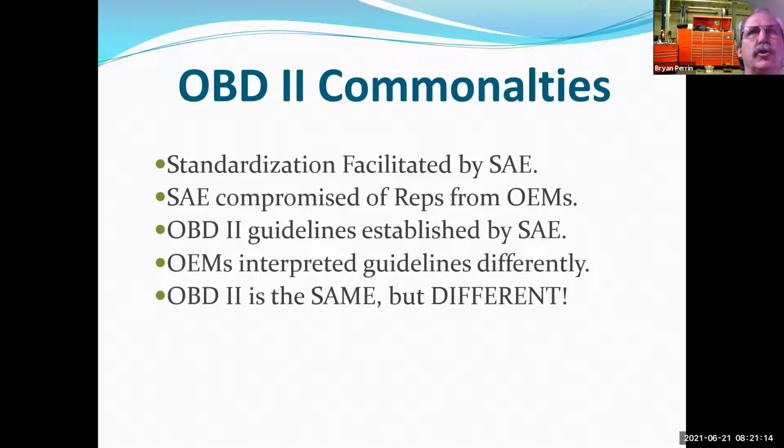Mitsubishi said twice, well, that's kind of a minimum standard. We want to really make sure that this system has problems, so we're going to test it 5 times. As a consequence, early OBD2 Mitsubishis would not set their self-test monitor, or their OBD2 monitor, because it would never get to that 5 times. So it wasn't a deliberate attempt to get around the rules. It was, again, misinterpretation. If I say something in this room and we're all speaking English, we're still going to have misunderstandings.